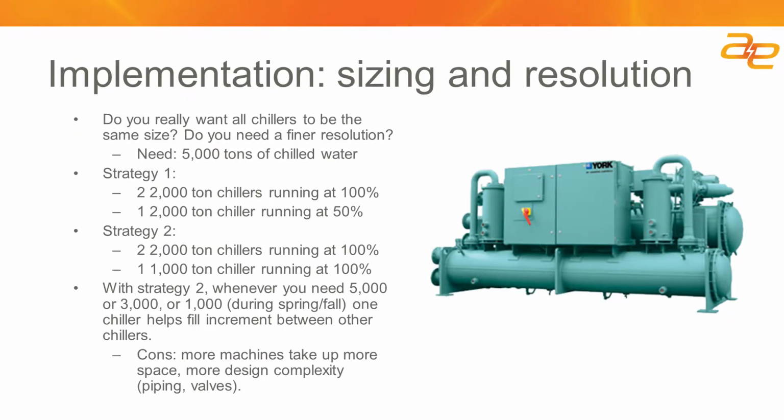So let's talk a little bit about implementation. So when we talk about implementation, there's a couple considerations that we need to pay attention to. The first is talking about sizing and resolution. So if you're in an existing facility, you may not have the ability to necessarily size your existing equipment. You may be stuck with what you currently have, so you have to take a different approach in terms of looking at your control sequence.